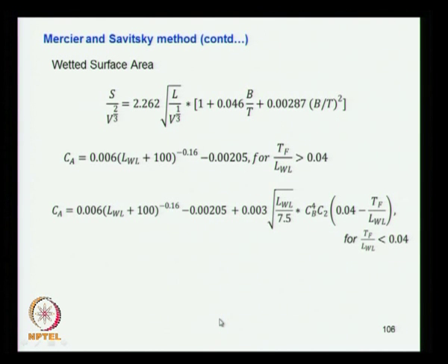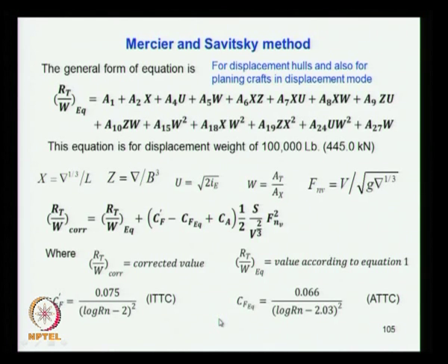It is not that you have split in this formula, the total resistance is handled, unlike the previous expressions where only the residual resistance was considered, whereas in this case you have considered residual resistance, also the CF value is also taken care of in this value.